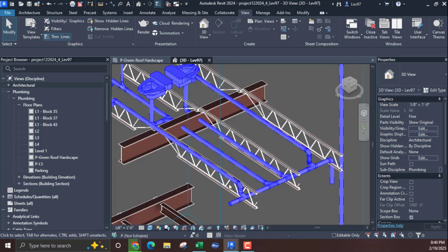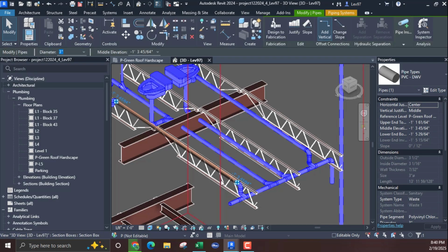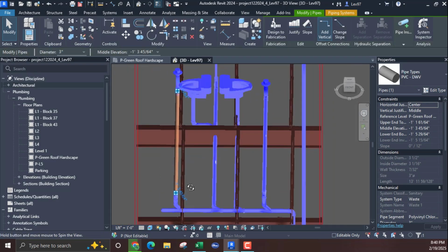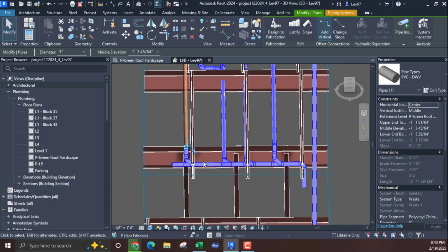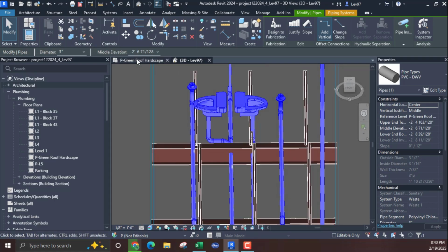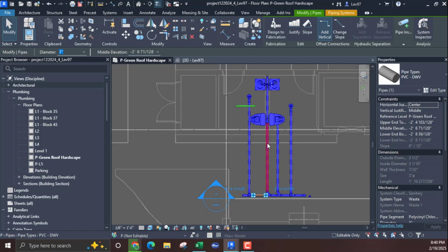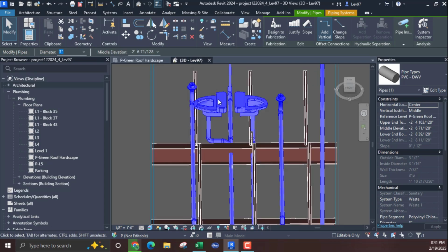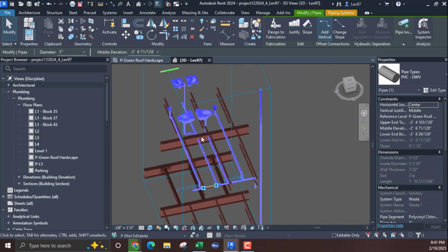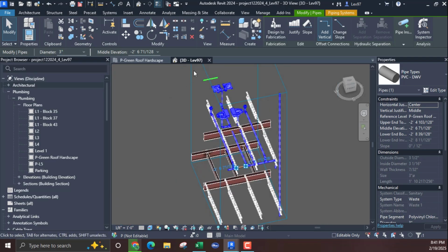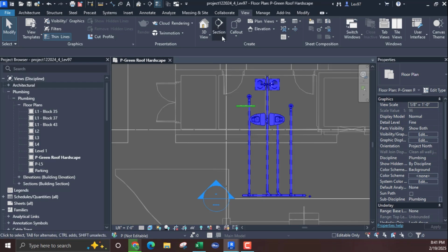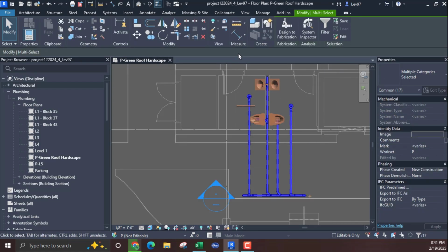And I think that the last time, what I was saying was what I'm going to need to do. I don't think I need to come all the way down to this main pipe. What I'm going to do is cross over somewhere in here and connect my two floor drains with this pipe that's coming off of my two water closets. So it's a good idea to have this view, right?